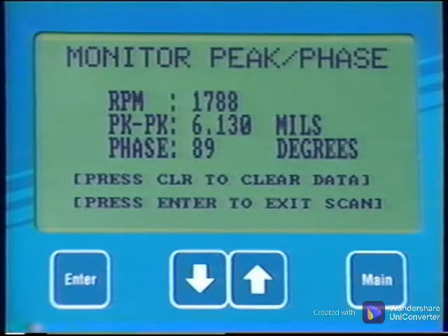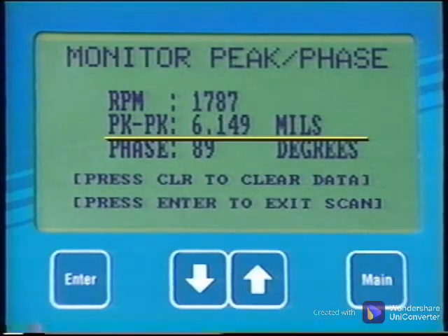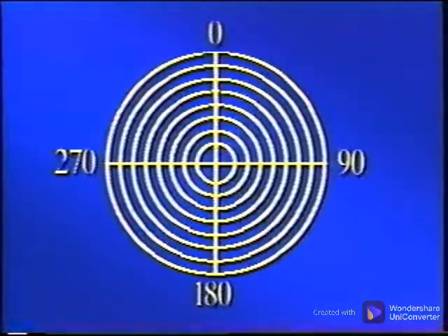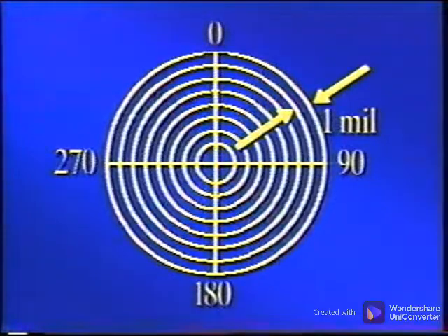The balancing phase data can also be displayed graphically as vectors since the measurements have both amount and direction. The amount is the measured vibration due to the unbalance within the machine. The angle helps us locate the unbalanced mass so we can know where to place the correction weights. The amount and direction can be drawn on a polar chart, which has the 360 degrees of a circle, and the spacing of the lines can be set to any scale needed for your balance job. Here we will let each space represent a vibration amount of 1 mil.